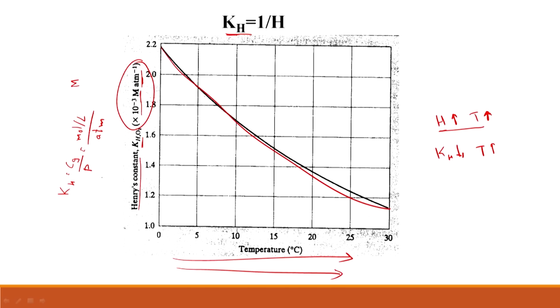So, what does that mean? When I increase the temperature, the concentration in the aqueous phase, the concentration in the water, decreases. So, what is the practical importance or relevance of this aspect? Typically in summers, you are going to have high temperatures, and you are going to have a considerably higher rate of biological degradation of any organics that you put into the river.